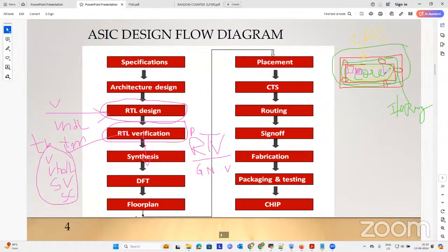And if there are any macros, macros are nothing but another part of a design. If we consider an example of system on chip, the system on chip has RAM, ROM, processor, and bus protocols and interfaces. Similarly, we have standard cells that are Verilog netlist gates and macros. Macros are nothing but another chip design that are soft macros or hard macros. Based on the soft macros or hard macros, we will instantiate in the core area. That is called placement.